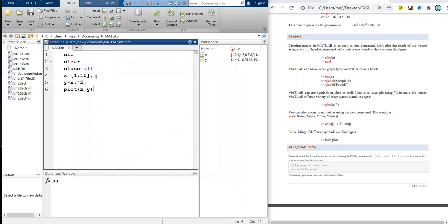I want to show a title. What I will do, guys, before the plot, I will use hold on to hold all components in one figure. So hold on to keep the same graph in the plot. So I plot x, y followed by the title. I will use a built-in function called title. It accepts a string in MATLAB within two single quotation marks, not double quotation like in C. We can say, for example, plot example.